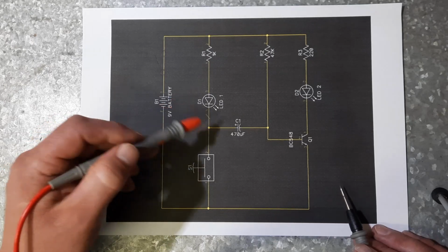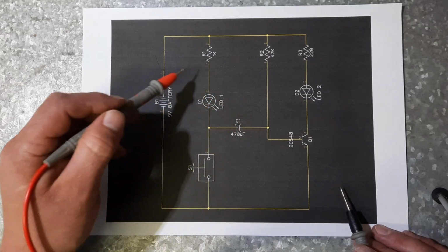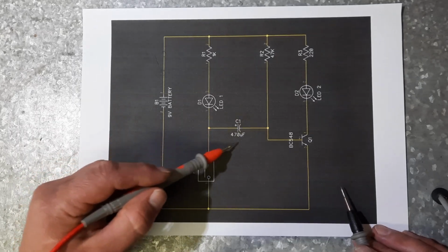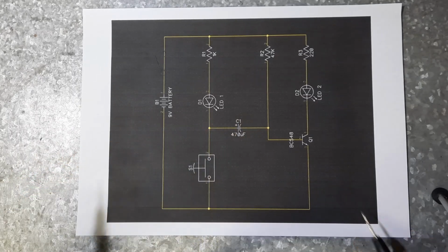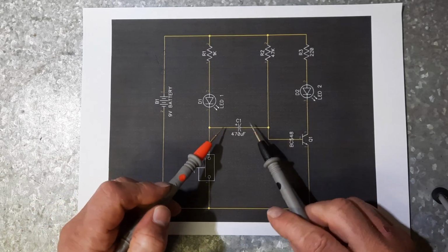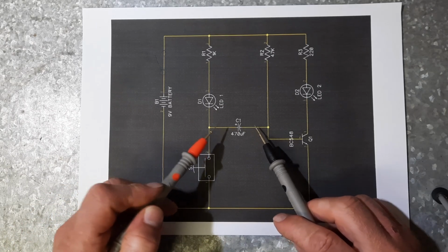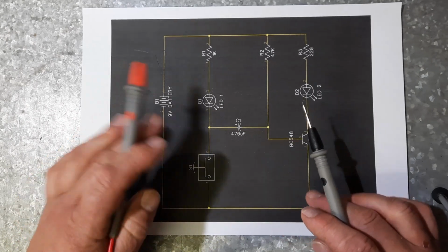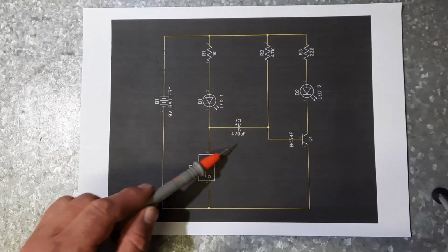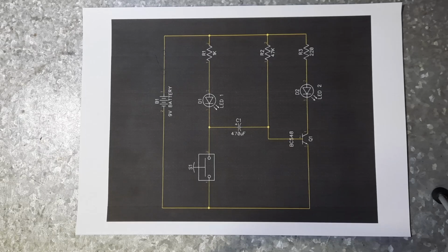But in its equilibrium state, there is no current flowing from here down to here, because this cap is as charged as it's going to get. If we took a voltmeter and measured across this capacitor while this circuit was on, and once it had reached its equilibrium, we would measure about 7 volts across this capacitor.